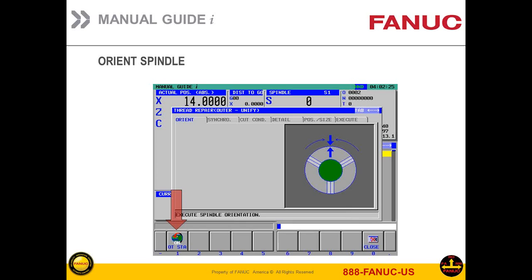However, just turning on the option within the machine to make it work is not enough. The builder of your machine has to do ladder development to make sure that it will work with the option. They have to develop their ladder to make sure all the right buttons work. And the reason we don't do it with our standard ladder is because all the machines are different out there.